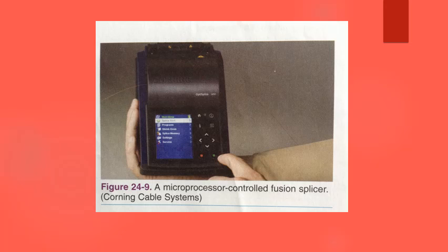The connector materials used for sealing the connector, air, all glass and plastic core materials, sealing materials, and air have different refraction indices or properties. This type of loss can be minimized by using a sealing material with a refraction index that closely matches the index of the glass or plastic fiber optic core material.